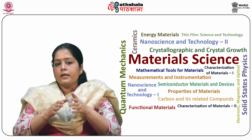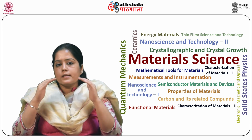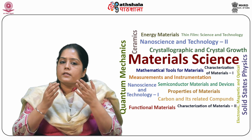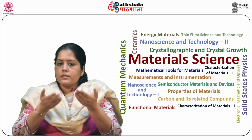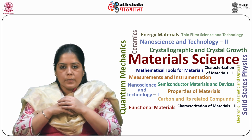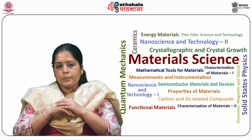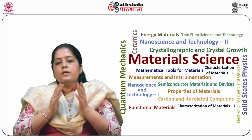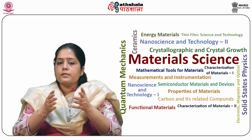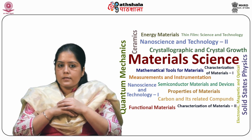Now let us discuss gallium arsenide solar cells. The direct band gap of gallium arsenide can absorb sunlight very quickly after it enters. The deposition techniques to deposit gallium arsenide include molecular beam epitaxy MBE, MOCVD, CVD and LPE. Homo, hetero, stacked, multi-junction, tandem junction and PEC structures are possible in the case of gallium arsenide solar cells.